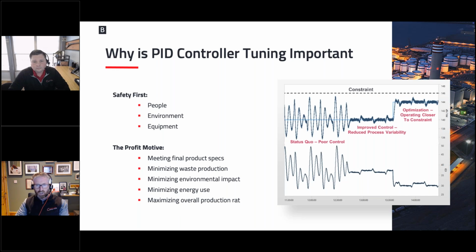I suppose the 3 phases of that trend, you can quite clearly see the loop was not in control and it was away from set point. But in that middle section there, I regularly ask customers, so why are you controlling at that set point? Because we always have been. Or why is it in manual? Because it always has been. It's habituated into it.